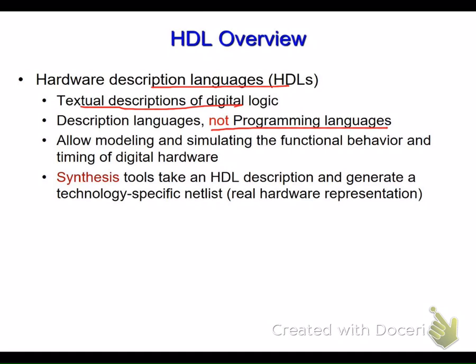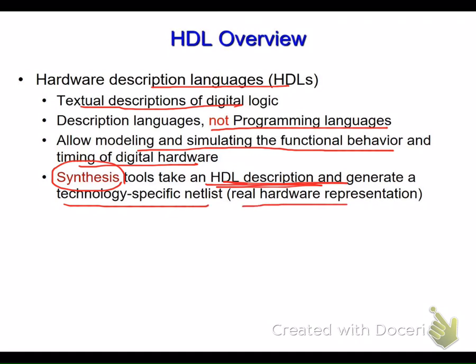It allows you to do modeling and simulating the functional behavior and timing of digital hardware. There are also, as I mentioned, the synthesis tools that will take whatever you wrote, its HDL description, and generate the technology-specific netlist, or in another way, the real hardware representation of whatever you are defining.